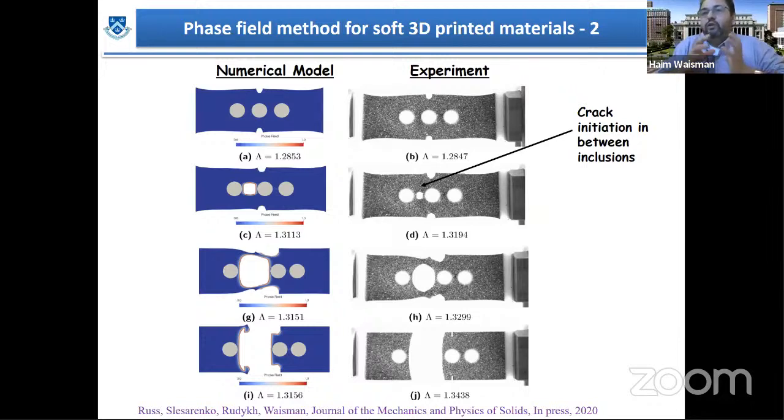If I would use a discrete formulation for this problem, then I may be in trouble, because I'm going to have a lot of little cracks and a lot of XFEM, and it's going to be very hard to track all the fragments. But if you're using a continuum formulation, I don't see any problems other than that computationally it will be expensive. It will not be a problem to trace all the little fragments. Okay.